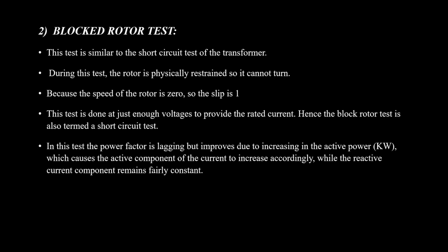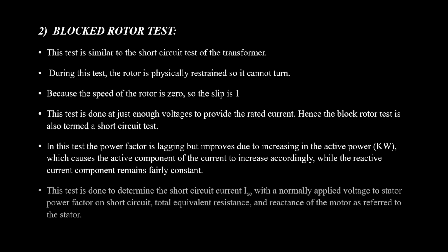In this test, the power factor is lagging but improves due to an increase in the active power, which causes the active component of the current to increase accordingly while the reactive current component remains fairly constant. This test is done to determine the short circuit current with a normally applied voltage to the stator, the power factor on short circuit, and the total equivalent resistance and reactance of the motor as referred to the stator.